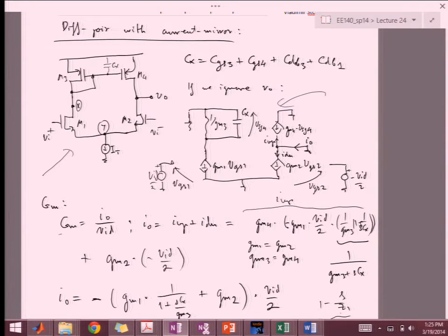Yeah. So, open circuit time constant. I'm assuming that this Cx is bigger than anything else, because it's kind of a sum of a lot of transistor parasitics, and in the other places I have only one or so. So I'll keep everything else open and just look at what it does. The inputs are going to be at 0, so these sources are dead.